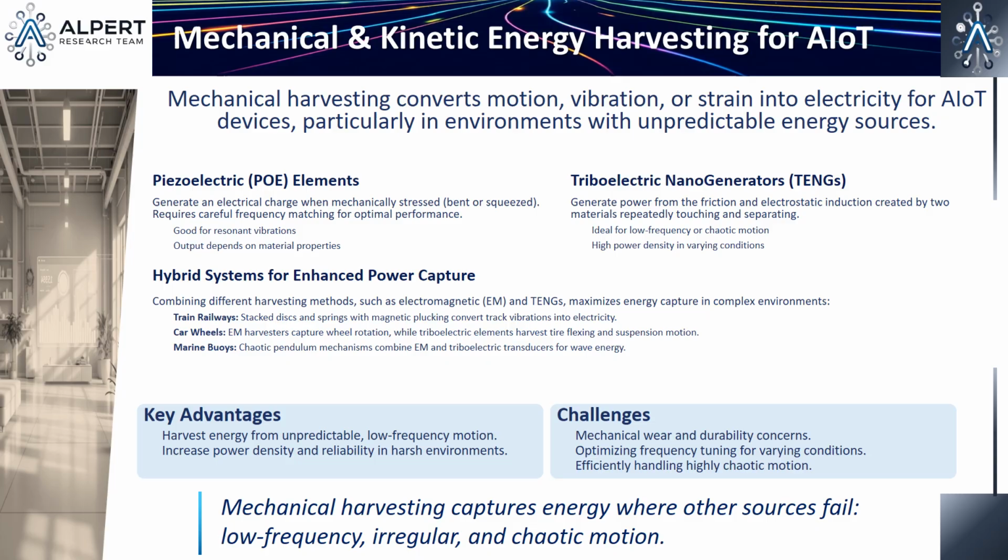It's a bit more than just friction. It's a combination of what's called triboelectrification, which is the static charge that builds up when 2 different materials touch and separate, and electrostatic induction. So as the 2 materials move apart, you create a charge imbalance, a difference in electrical potential, and that drives a current. They're fantastic for harvesting low-frequency, irregular motion, like someone walking. But the key technique in many of these is called magnetic plucking. What's that? It uses magnets to quickly snap the harvesting element back and forth. This increases the energy you get, but it also reduces mechanical wear, which is obviously critical if you want this thing to last for 20 years on a bridge.